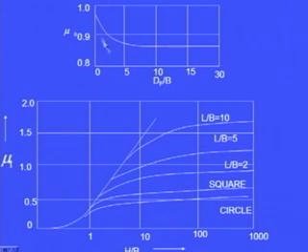So, this is the figure which shows the relationship between mu0 and Df upon B. This figure shows the relationship between mu1 and H by B for different types of foundations, like this is for the circular, this is for the square, these are for the rectangular when L by B ratio is 2, L by B is 5 and L by B is 10.